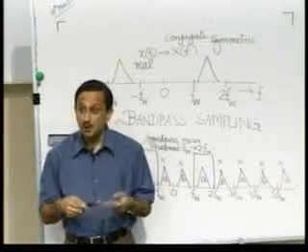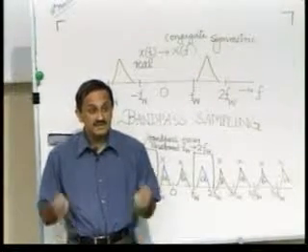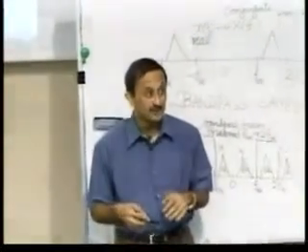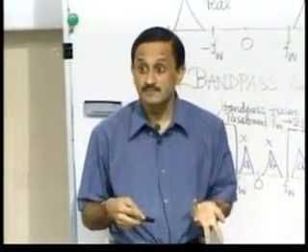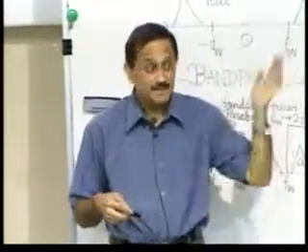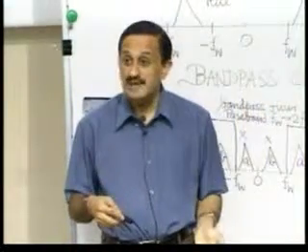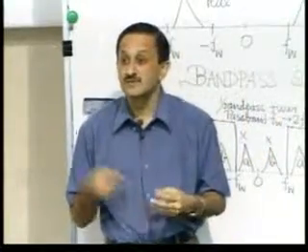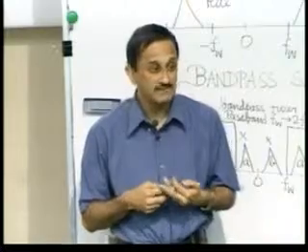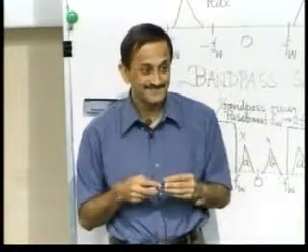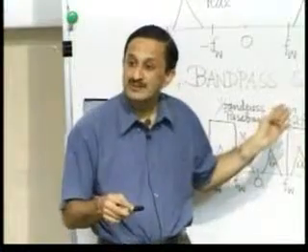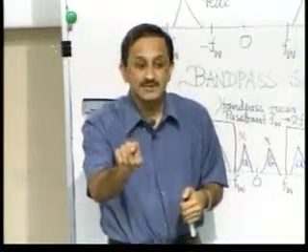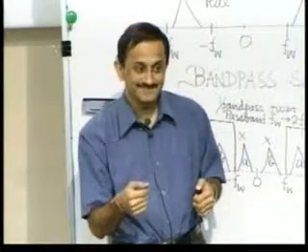For example, if you know a priori that your signal is a sine wave of frequency 50 hertz with an amplitude of 2 volts and a phase of 0, you don't need to sample at all. That's an extreme case. Or if you know a priori that your signal is an exponentially decaying pattern with a decay time constant of 2 units of time, whatever they might be, you don't need to sample at all. Indirectly, what we've been doing in the last few minutes is to introduce a little more a priori information and therefore reduce the amount of sampling.